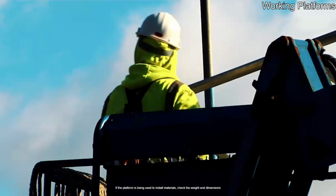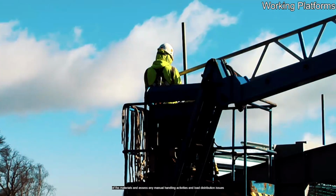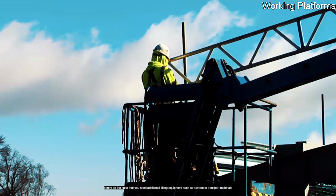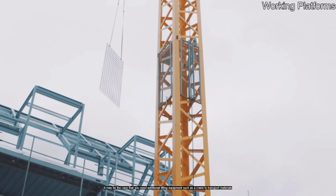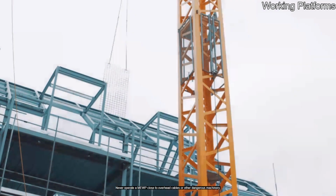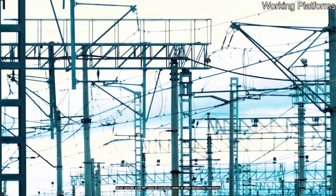If the platform is being used to install materials, check the weight and dimensions of the materials and assess any manual handling activities and load distribution issues. It may be the case that you need additional lifting equipment, such as a crane, to transport materials into position before work can proceed. Never operate an MEWP close to overhead cables or other dangerous machinery.